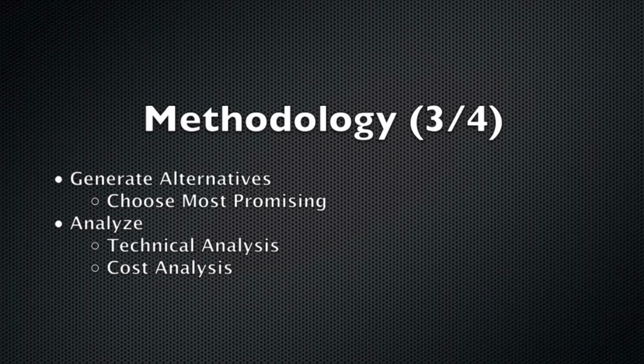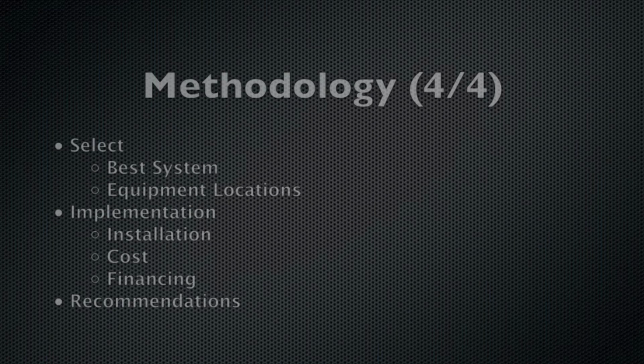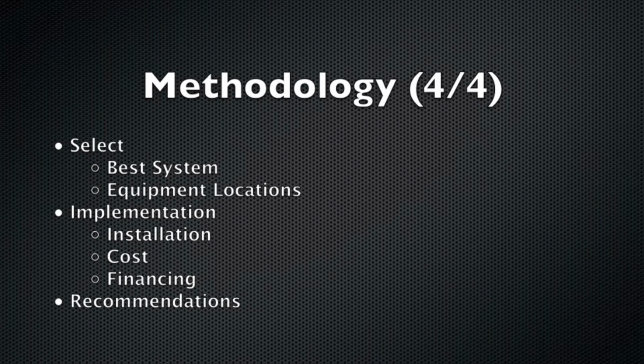The second would be a more in-depth cost analysis. The different inputs would be lifespan, equipment cost, energy efficiency and consumption, installation, maintenance, and environmental impact. Once the analysis is done, the best system can be chosen for design. Then the locations for any outdoor and indoor equipment will be marked on plans.